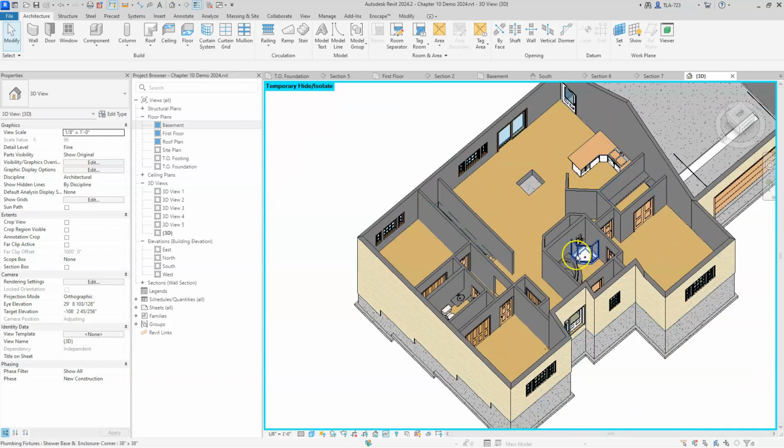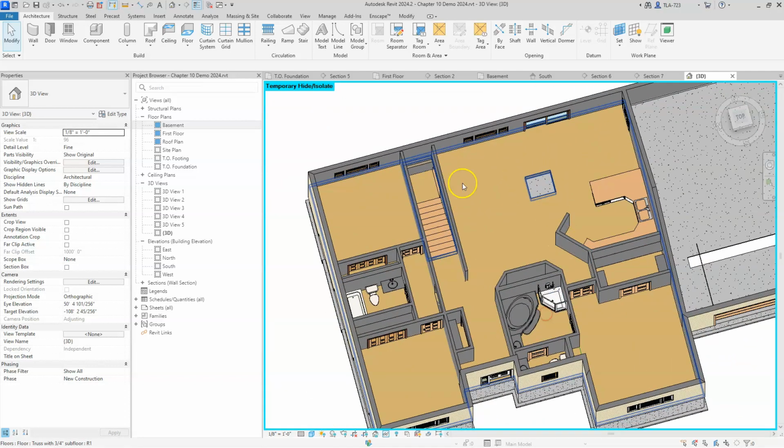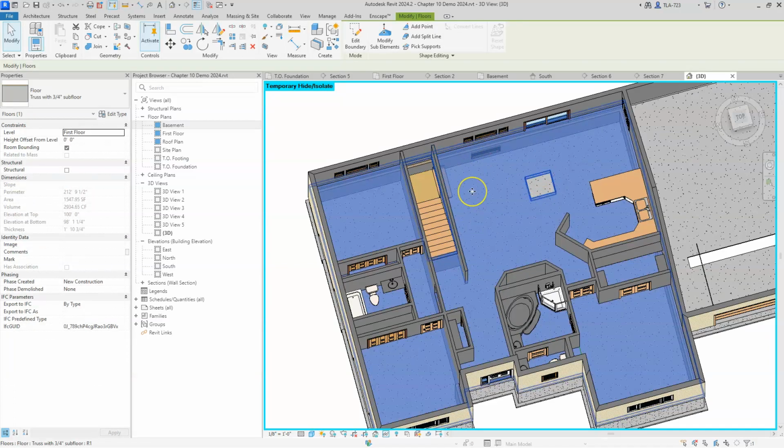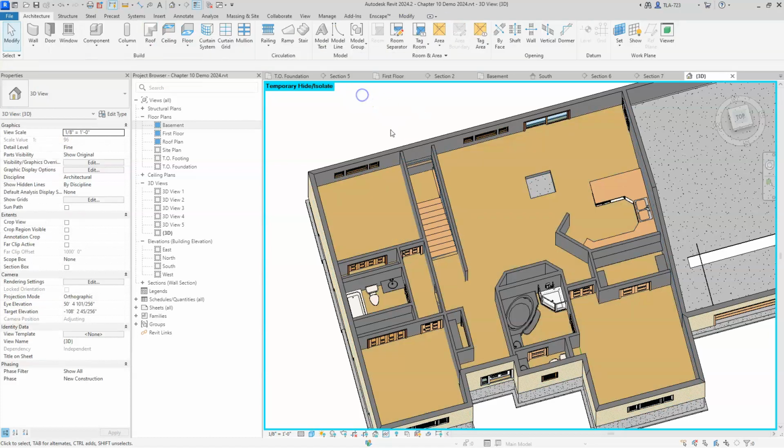So when would we use that instead of just changing the profile of the floor? Well, typically we're going to use a shaft when we're spanning a lot of floors. So if we're creating an elevator shaft in a building, for example, it would be better practice to create a shaft, because otherwise you're going to have to edit every single individual floor. And it's really easy to make a mistake or get that opening that passes through all of them misaligned on 1 or 2 floors and not realize it. So best practice would be to use a shaft opening. You can adjust the size, the position, and it will conform to all the floors that it passes through automatically.